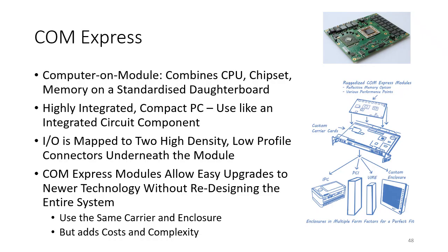And I think what a lot of people found was, yeah, ComExpress does give you some flexibility, but ultimately a monolithic design, certainly if you're talking about higher volume designs, a monolithic design allows you to have a more effective design with fewer components. There would just be one PCB, there would just be all of the chips on the single board. Certainly as we move towards more system on chip type applications now, the whole idea of having a ComExpress board is going away to some extent.